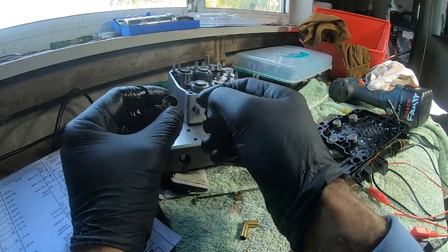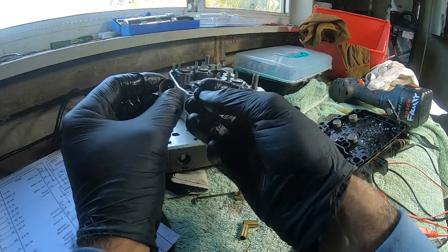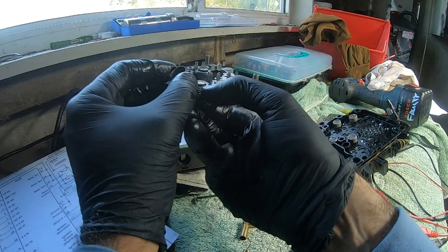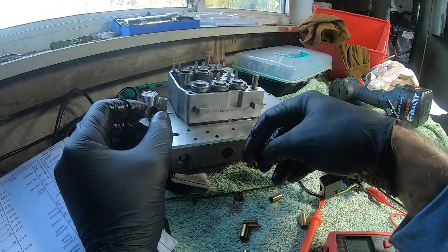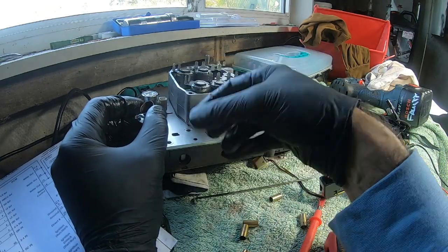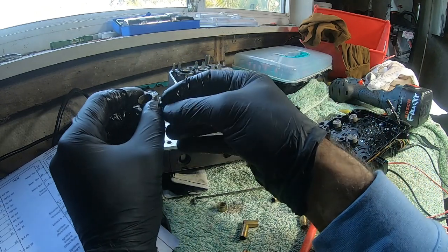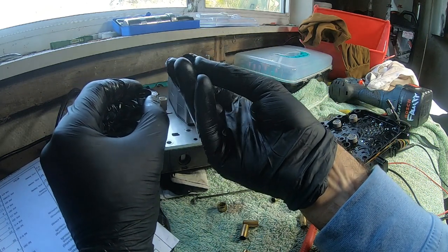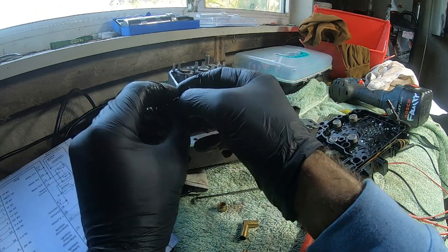Things that can go wrong: these holes, if they are obstructed, obviously the fluid will not come in and will not push this thing. This thing, if broken, which is not in my case, will let the fluid come directly to the brass contact without building any pressure on it. So I've looked at these 2 things, they are good to go. When you're putting it back, just make sure that the cup side of this rubber ring or seat goes downwards.